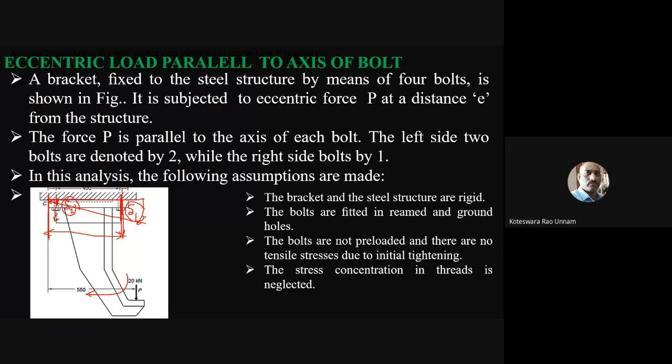So therefore, you always need to consider the bolt which has the highest deformation, or which is far away from the tilting point. So we won't consider this. We'll consider only this set of bolts because these bolts are far away from the tilting point. Once you identify that, then we need to identify the force: because of this movement, what is the tensile force acting on this set of bolts.